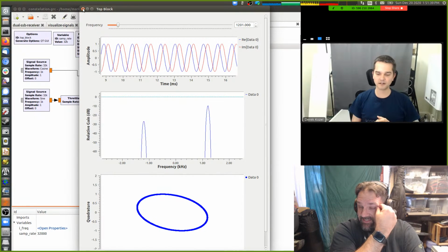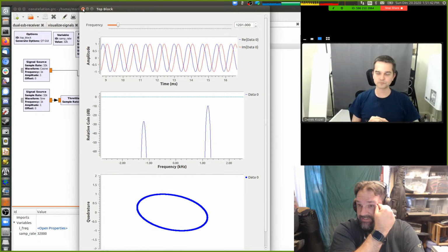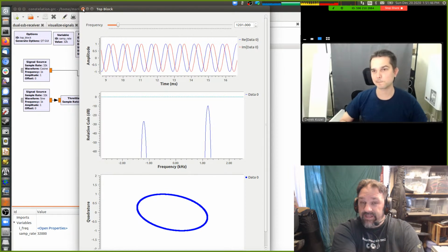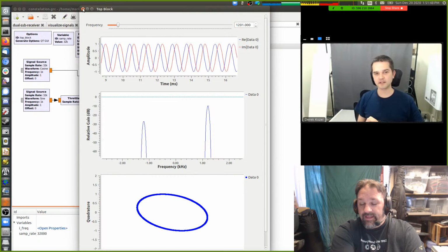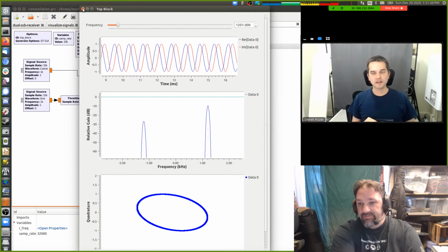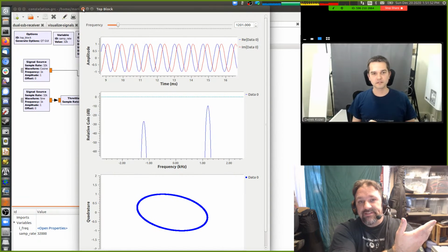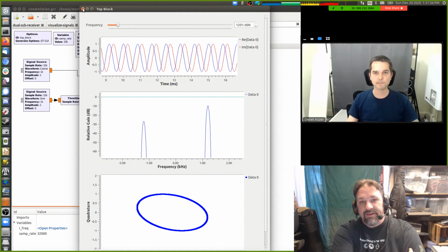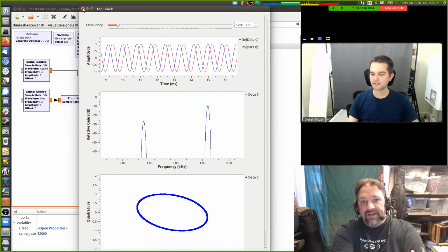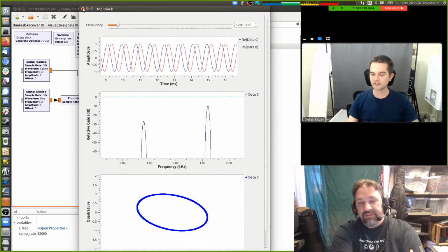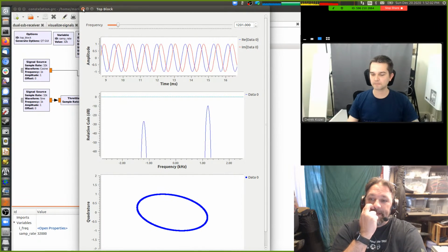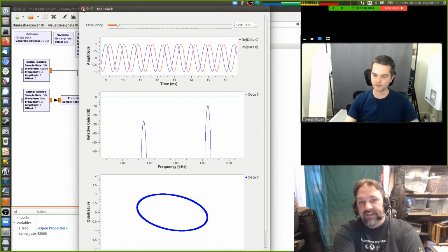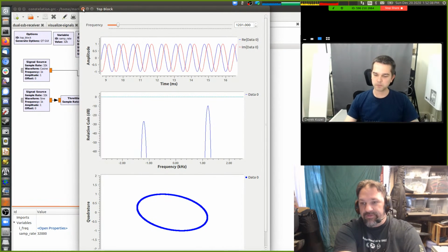It's a design decision. You can either design your DAC and your mixer as a quadrature mixer, or you can design it as a standard heterodyne. Like a standard single sideband radio, like my BitX 40. It takes a microphone and mixes it with a local oscillator. You get the positive and negative images. You run it through a little tiny filter to filter out one of the two sidebands, and then you shift that up to the frequency you care about, amplify it, and transmit it. There's no I and Q there.